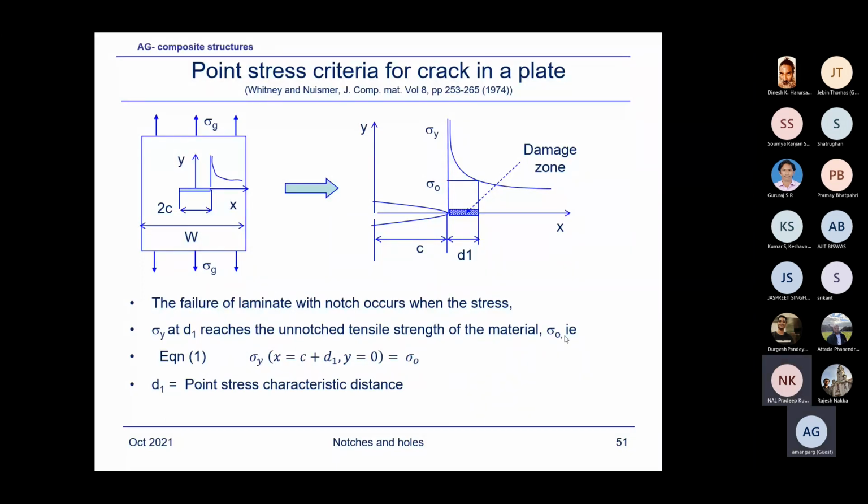On the right of this, I show a pictorial representation of the stress near the notch tip, varying from the notch tip to away from the notch tip. As you can see, right near the notch tip, the stress theoretically goes to infinity, because it's a stress singularity at the notch tip.